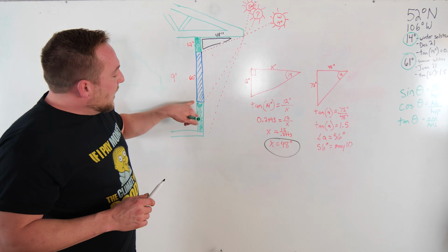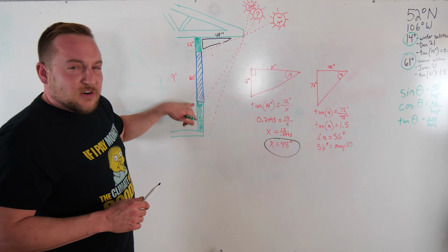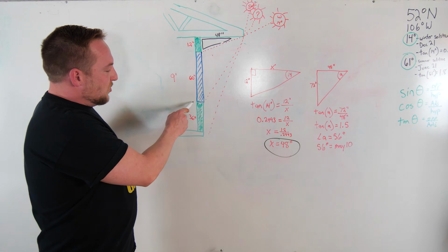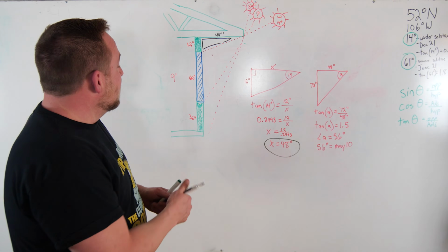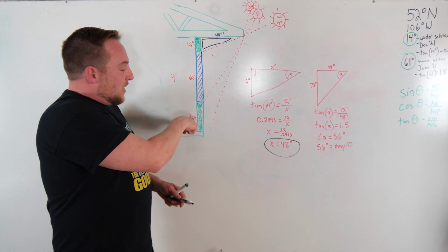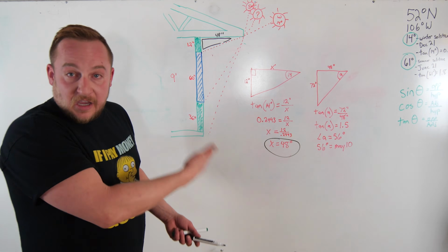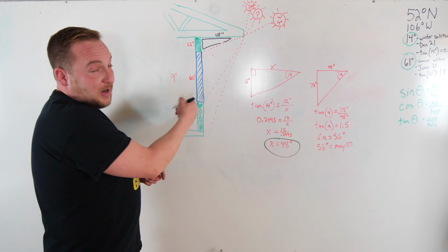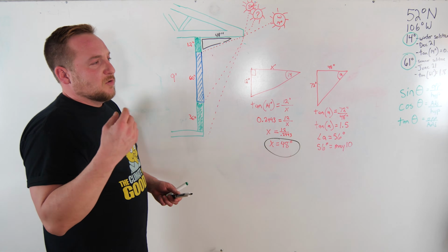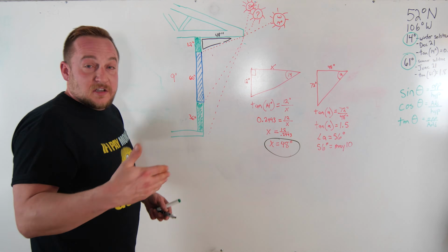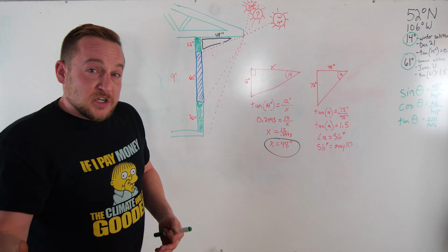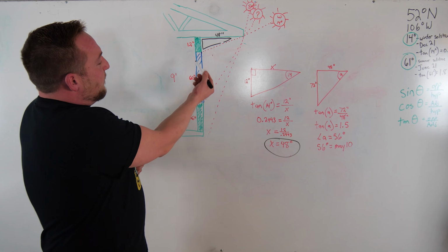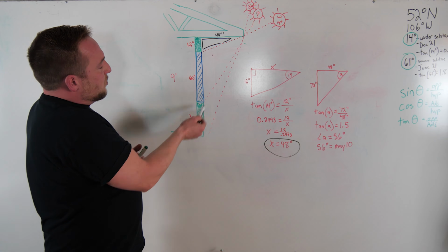So below the window, I wanted 36 inches. On one of my south windows, I have a countertop, and 36 is countertop height. On another one, I have the back of a piece of furniture, a couch, and I don't want glazing behind that. It's going to give you frost and condensation issues in the winter. So you have to deal with function as well. But so, 36, we know that in here.